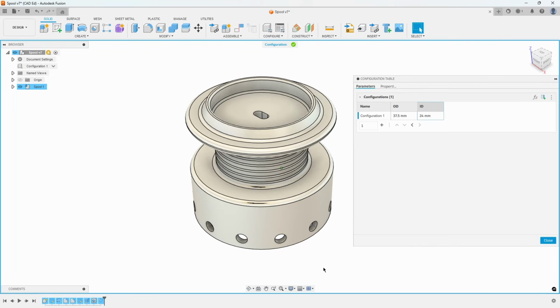Refer to Exhibit 1. Next, click on the Hole feature in the timeline. A hole configuration dialog will appear. Click on Suppression and Diameter in the dialog. This will allow us to either turn the holes on or off in the design or to change their diameter. Press OK and then click on the Pattern feature in the timeline and select the Quantity option and press OK.